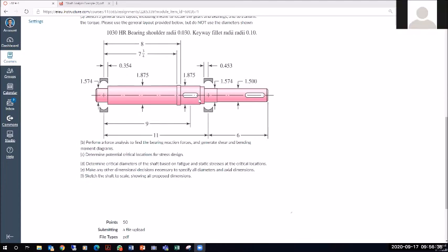Yes. Okay, so yes, you will need to check at the end of the keyway, and you're going to need to check at the shoulder if your maximum moment, and also looking at the bearing, you're going to have a high bending moment and a shoulder. So you'll be calculating this lowercase d, this uppercase D, and you probably want to verify every time there is a change in the geometry. But I know that this is going to be kind of the most critical area, so that's why I think it's not going to be as lengthy as the example we just did.